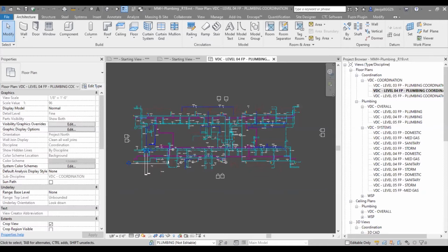And then the coordination side of that within VDC, once we get it into the contracting world, is making sure that, being that we have these families in the models at actual size and we're actively coordinating, if you've got a 60-inch flat screen going up on a wall, we don't have a light fixture that may be hanging 2 feet down from the ceiling. We're going to make sure that light fixture is not impeding the vision of that monitor.